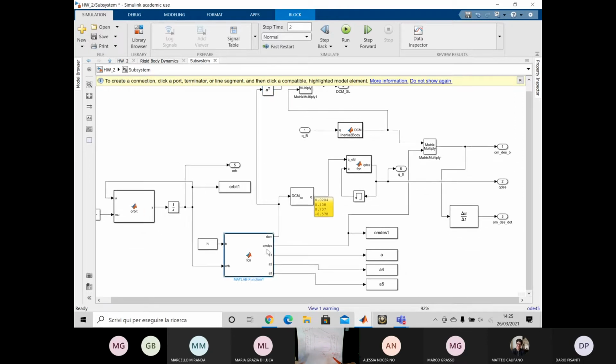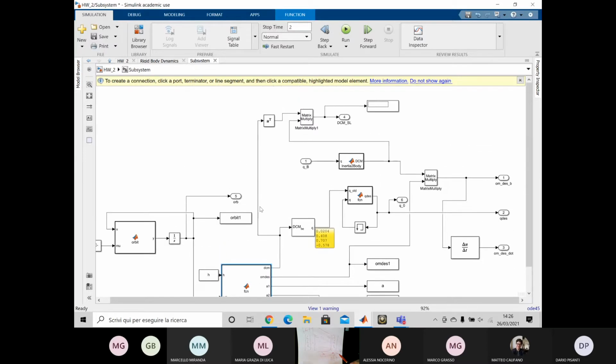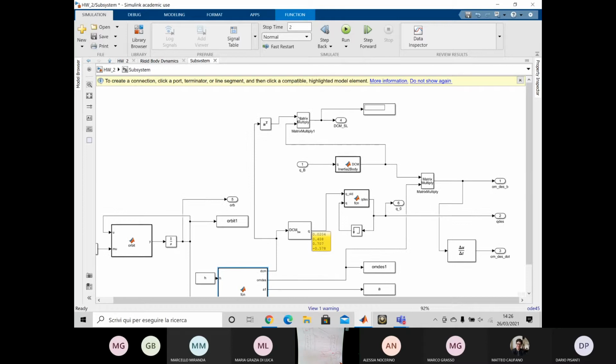Okay, just to recap. Here we have the DCM from inertial to LVLH. Then this is transposed, so it becomes from LVLH to inertial, and that is multiplied. This one is inertial to spacecraft. Yeah, inertial to body. And so the order of that multiplication is incorrect. Ah, okay. Yeah. I think, right?